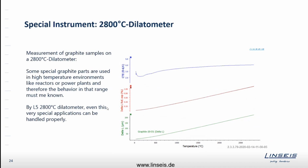Then I have some typical examples for the special configurations. This measurement here is the expansion of a graphite sample with a 2800 degrees Celsius ultra high temperature graphite dilatometer. That's relevant when it comes to cathode research, graphite research, and some very special metals require that kind of temperature range. It's just to show you that we can really go up to 2800 with a graphite furnace. It's nothing special. It's just an example for that kind of measurement.